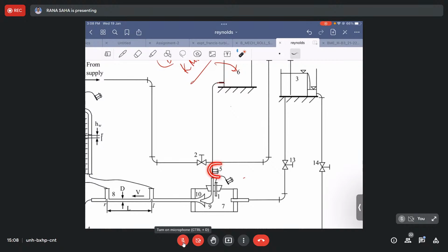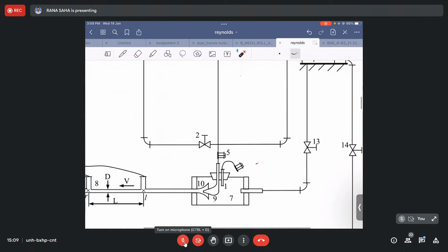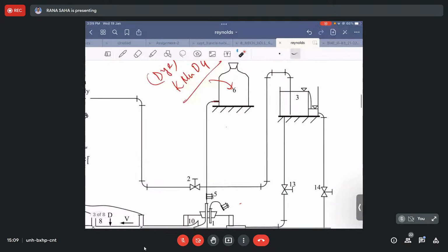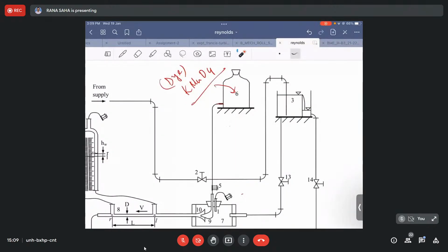Once you have this pipe, that is another, it's a kind of a pinch valve or a cork valve. If you rotate it, then this particular pipe, which is a flexible pipe, I mean, this valve presses the pipe and the flow can be stopped. So if you rotate the screw, then it will basically unpress the pipe and thereby the flow of dye will occur. And this is just due to gravity, it will start falling. And here there is no question of maintaining constant head or something like that. If you emptied this bottle, again you need to fill it. And so that's the thing. It is just to mix the dye particles with the water. So typically the main motion of the water will carry the dye particles with it.